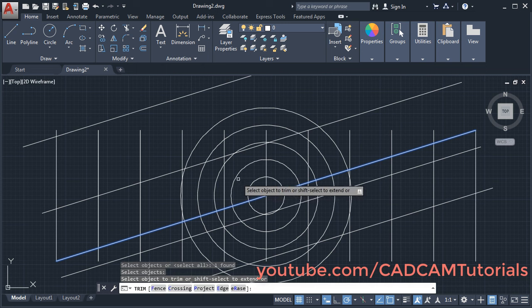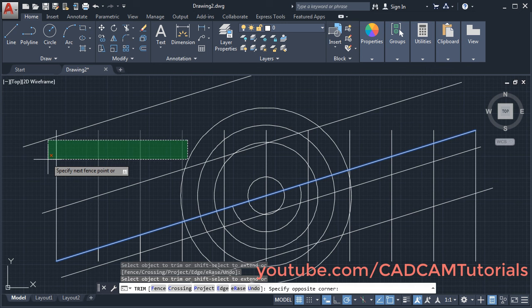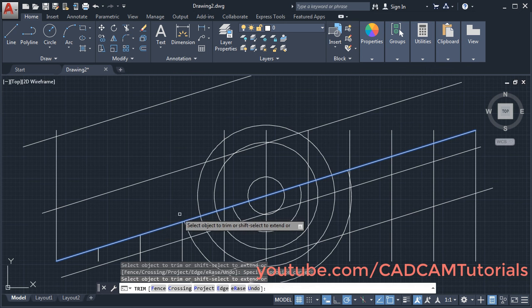I want to trim this circle. Click there, so that much of the circle will be trimmed. So now this line is selected. You can trim other objects also. And if you want to trim multiple objects, then you will have to click in empty space and take your cursor to the left side. That means click on the right side and take your cursor to the left side. So whatever objects have been crossed, those will be trimmed. Click there. So three lines and this circle have been trimmed. Then to stop the trim command, you will have to press enter.